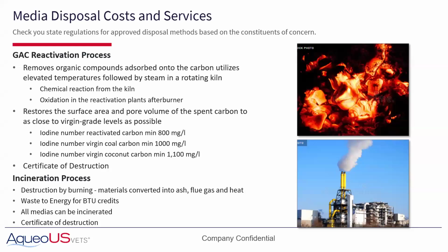Again, there's been some work being done, or has been done to show that it potentially can be reactivated. I'm aware of a couple places that are using potable water reactivated carbon from PFAS. One hasn't been very successful because they've had some metals leaching coming off the reactivated carbon. For it to be reactivated, you have to get your own carbon back too. This is a requirement within AWWA that the 20,000 pounds you took out of your system gets reactivated. They add makeup carbon because you lose about 10% when you do the reactivation.